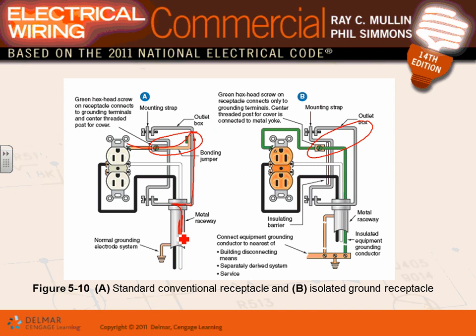For the receptacles labeled technology circuits in our project, which we're going to be laying out in a few seconds, they're calling for an isolated ground receptacle in all the technology circuits. Did you guys hear me? All the technology circuits must have an isolated ground receptacle. What does that do for a living? I don't know if you see, there's a little triangle here. Based on the specification, the manufacturer puts an orange triangle on them to identify that this receptacle is actually an isolated ground receptacle.